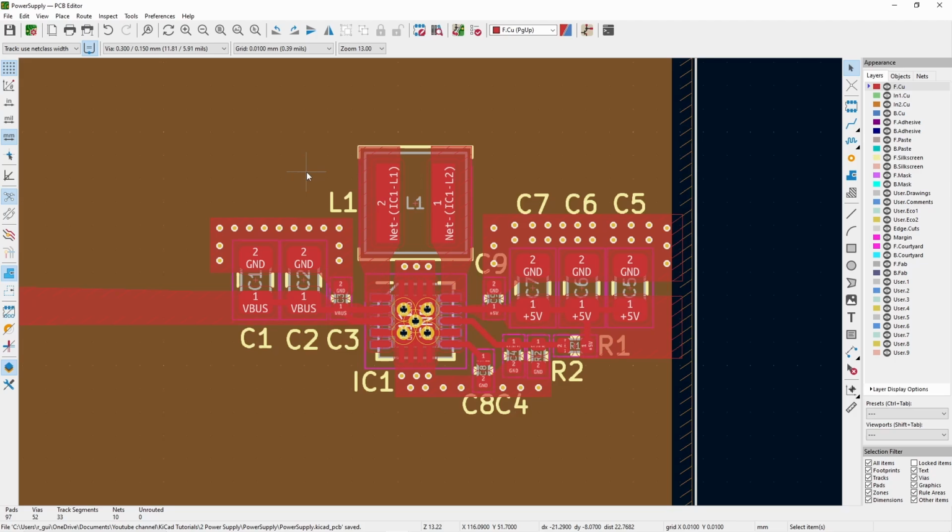The last thing to do is check the inductor, because obviously I selected a random size at the beginning. So what I'll do is go to my bill of materials, load up the inductor part number, and then create a new part for this inductor. I will still continue using, I think, the layout from the 3D model, because I think it's roughly the same size.